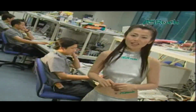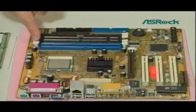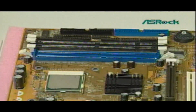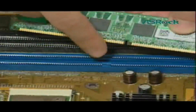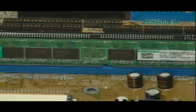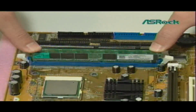Next, we are going to install a memory module onto a motherboard. Step 1. Unlock a DDR DIMM slot by pressing the retaining clip outward. Step 2. Align a DIMM on the slot, such that the notch on the DIMM matches the break on the slot. Step 3. Firmly insert the DIMM into the slot until the retaining clip snaps back in place.